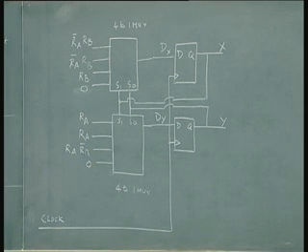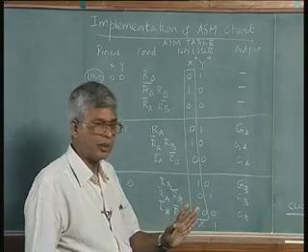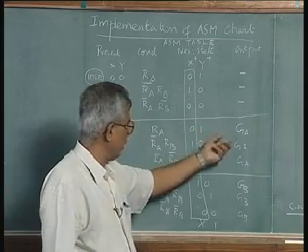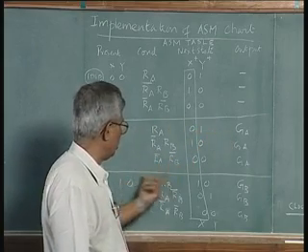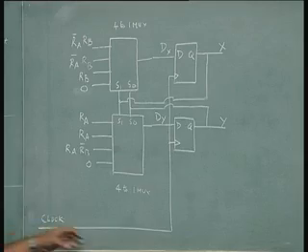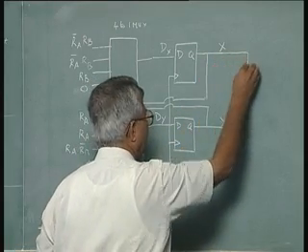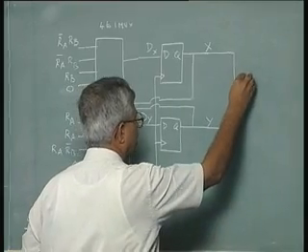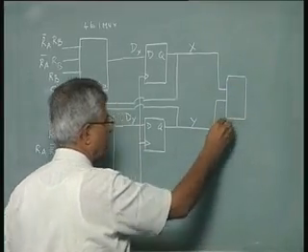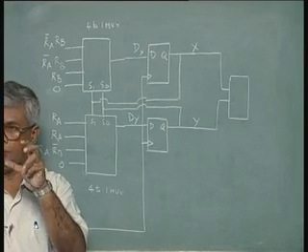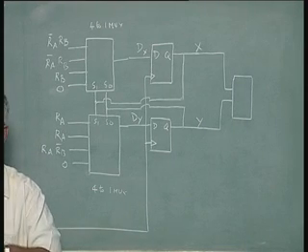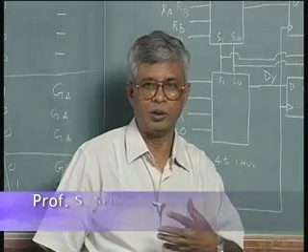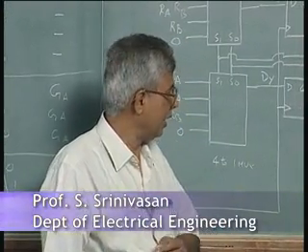And the output is now tied to states, that makes it easy. So, in state 0 0 there is no output, in state 0 1 the output is GA, in state 1 0 the output is GB. So, what we normally do to make the design simple, even though it is a little more expensive in terms of gate count, is this. We have already talked at length about reduction of the number of ICs compared to reduction of the number of gates, and how reducing the number of ICs is a more economical and practical solution, especially today in terms of IC design.